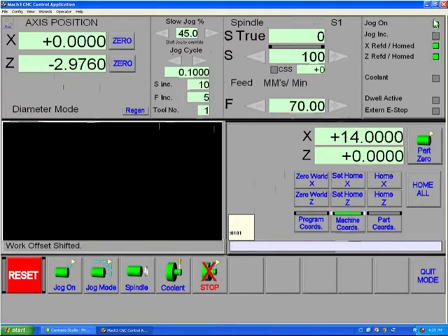The LEDs are simple. We have jog is on and allowed at the moment. You can see here that you can turn off the capability of jog in case you've set up your machine and you want to make sure that you don't make a mistake by pressing a key on the keyboard and thus throwing yourself out of a coordinated system. We have reference lights to show whether or not we have homed our machine. Mach3's options do allow for these homed lights to be left on, and if you don't have home switches, pressing home at any time will home you on the spot, and the system will then zero itself to that position.